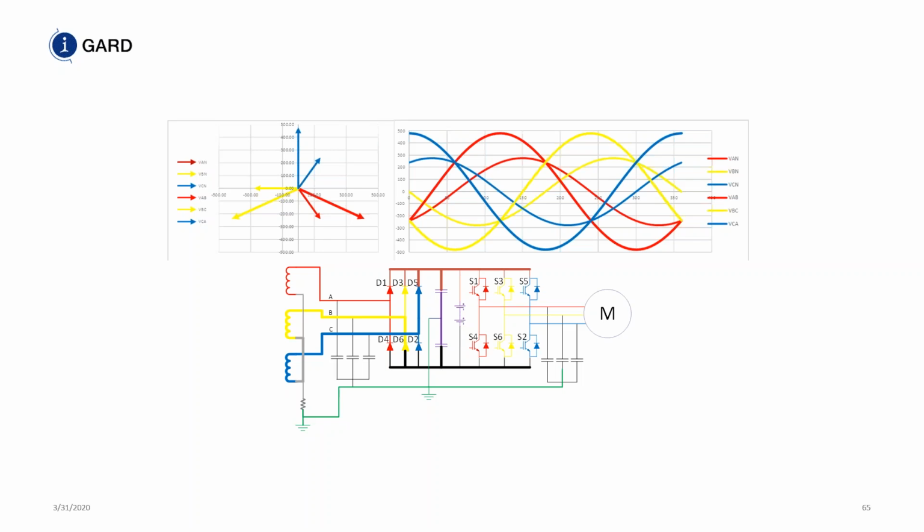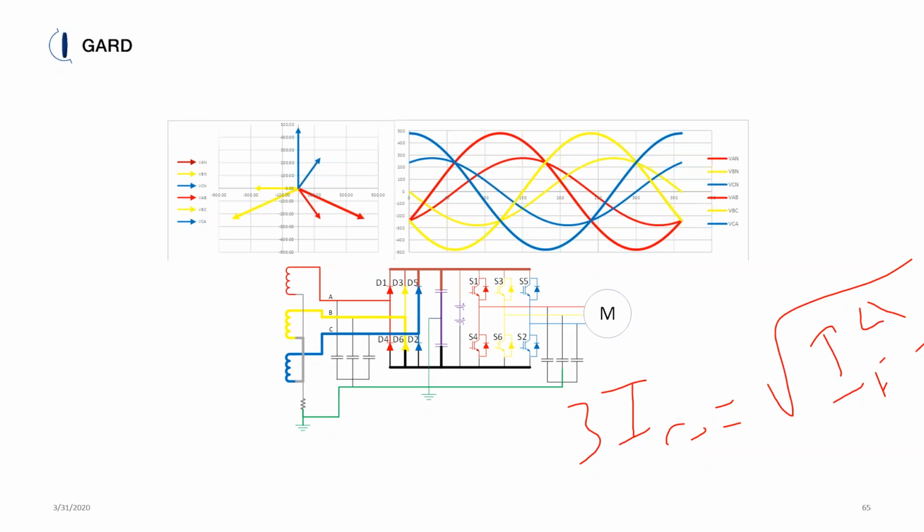If you have a resistance grounded system and you do the same thing, you put a fault on one of the phases, the fault current squared minus the resistive current squared, these things are all measurable, the square root of those two differences will give you the capacitive charging current. So let's see if I can write that down. 3IC0 is equal to the square root of IF squared minus IR squared. So it can be done.